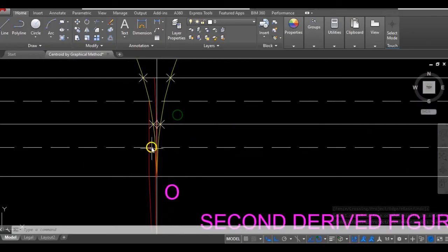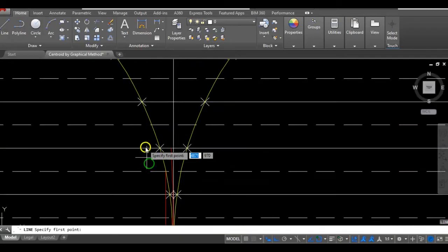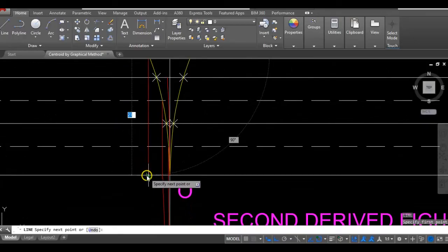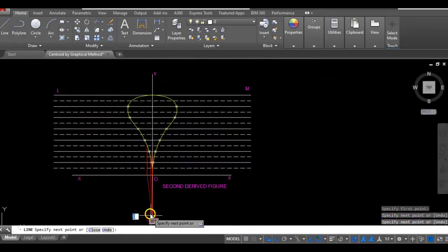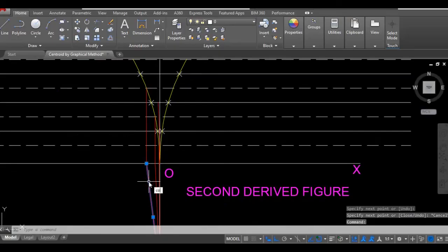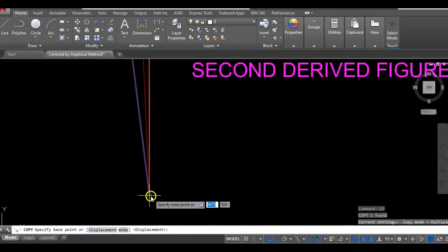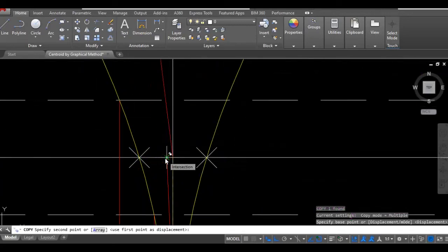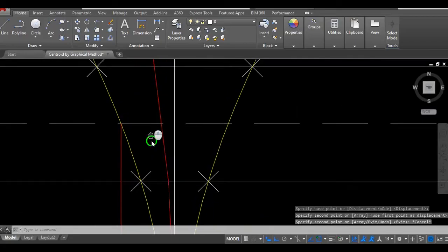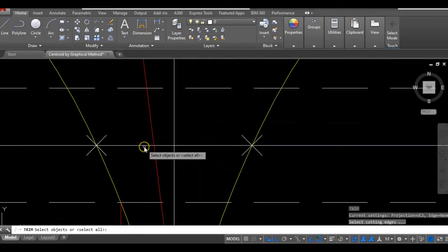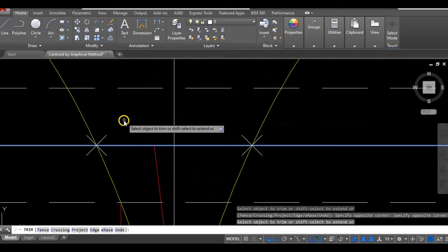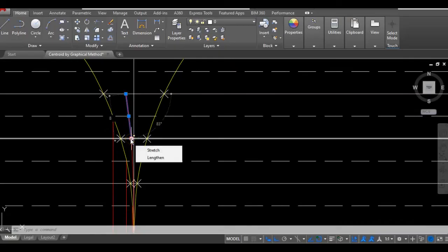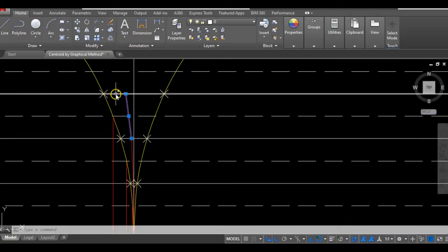And just in case I didn't say it before, or for emphasis, remember that after you have done this process, so you've carried your line down to your base, down to your pole, and then you're copying, when you paste it, you would recognize that you're pasting it at the ordinate below, the mid ordinate it's coming from, and then you are trimming it at the ordinate above where it's coming from. So let's go again. You're pasting it, here it is. Paste it at the ordinate below, trim it at the ordinate above.